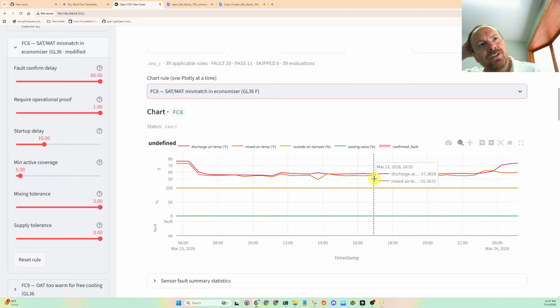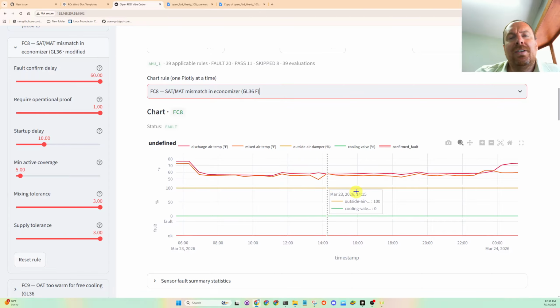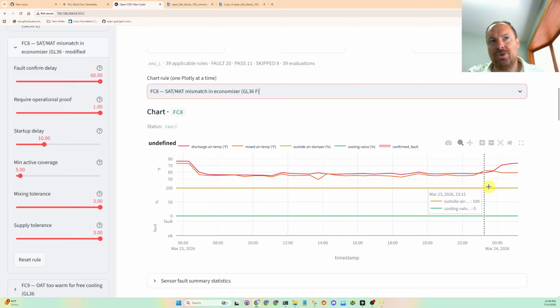Yeah, I have to ask that owner because something doesn't sit right, that this outside air damper is always 100%. Because you can see in the data that when the fan goes to zero static pressure, this never changes. I have a hunch that this is 100% closed all the time, and something's not right. It's either 100% closed all the time, and it just never opens.